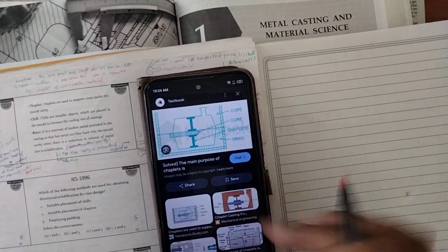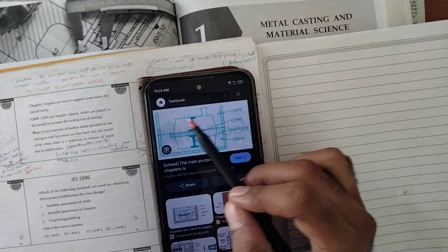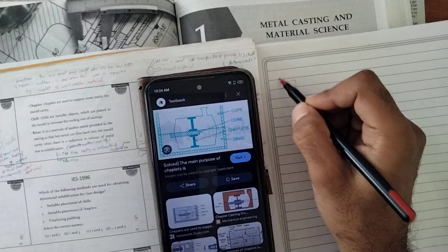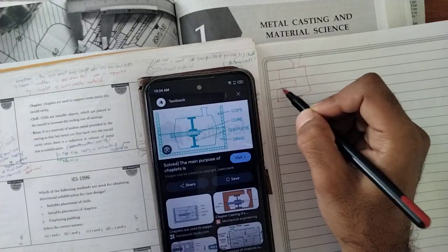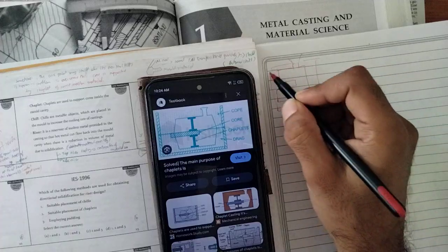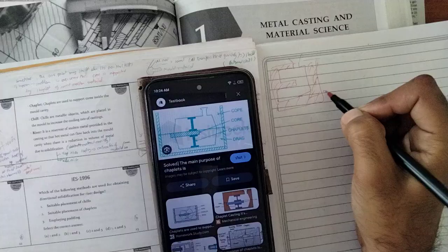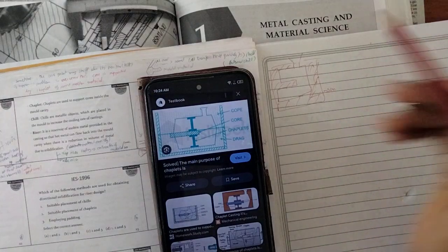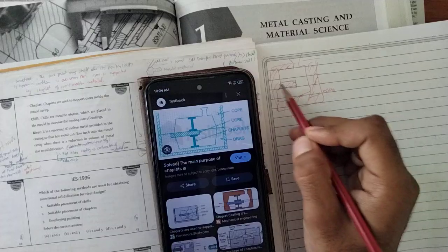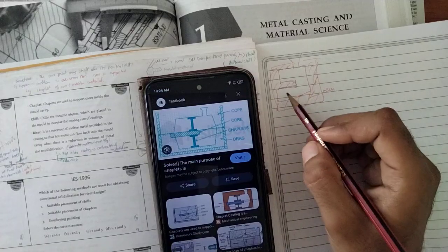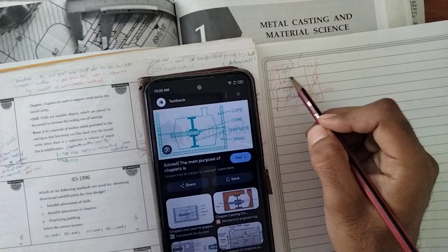So what generally we are doing is, we need this entire mold, for example, running like this, and this one is entirely placed like this. This is entirely sand. Suppose we did not use any kind of supporting material, this will definitely bend like this, and if it bends we couldn't get the required dimension. So what will they do? They will place supporting material, supports like chaplets. These are called chaplets.